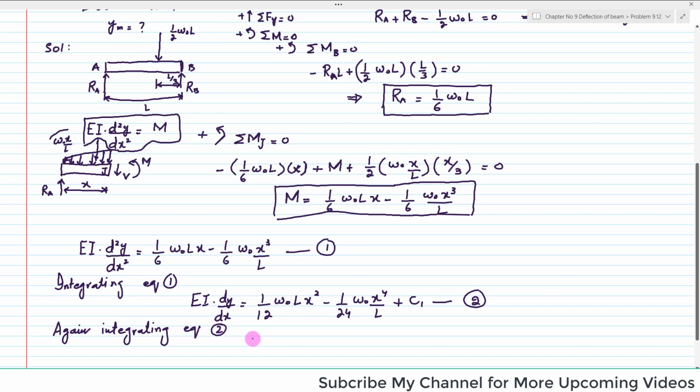So integrating equation 2, we will get EI into y is equal to 1 over 36 W naught L x cube. You must know how to take the integration: x4 will become x to the power 5, and below it is 5 into 24.